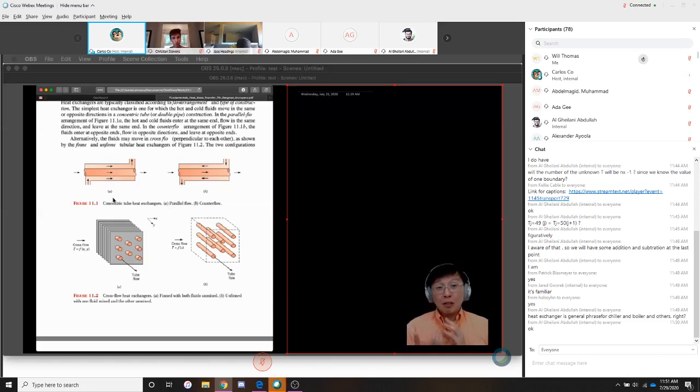Now, when that refrigerant is cold, you pass it through a heat exchanger to take away heat from another stream. So a chiller would have a heat exchanger. It does have at least one heat exchanger and a compressor. The reason I hesitated is that, in principle, a chiller has a minimum of 2 heat exchange points, but let's not go there.